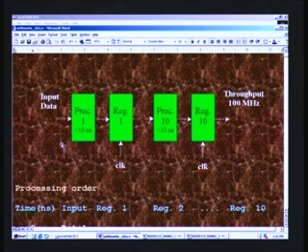Here in digital realms, instead of water we can assume data flowing into a pipe which is composed of not only processes but also registers, and we will see in a minute why these are separately indicated. That is the analogy we can draw for this digital pipeline, with the water pipeline as the analogy. What we claim, as we mentioned earlier, is that there is a possibility of improving the speed dramatically, say from 10 megahertz to 100 megahertz operation, just by pipelining and having the very same hardware.